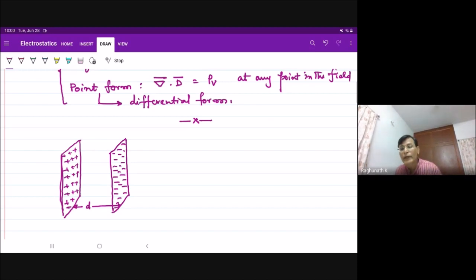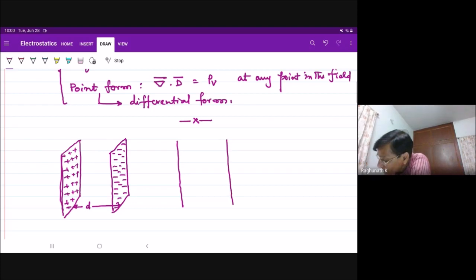I want you to understand it here because even if I go to PN junction, I am going to use this concept only. People derive the expression for field using Poisson's equations, all those things. But we will be in a position, because of this knowledge, to straight away talk about the field distribution in the junction. When I look at the front view of it, these two are just lines. Positive charge on the inner surface, definitely negative charge on the inner surface. This is the parallel plate capacitor charged.